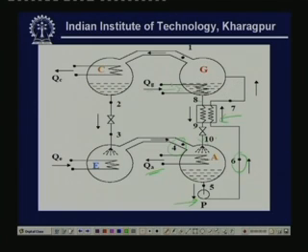As a result of this heat supply, refrigerant is separated from the solution. So, refrigerant at high pressure and high temperature goes to the condenser. In the condenser, it condenses, and the heat of condensation is rejected to a cooling water or a heat sink, and the condensed refrigerant liquid at high pressure is throttled in the expansion device to low pressure, and because of this the pressure and temperature drops. So, this low pressure low temperature refrigerant is sprayed into the evaporator, where it evaporates, taking heat from the external heat source. So, you get the useful refrigeration effect QE.